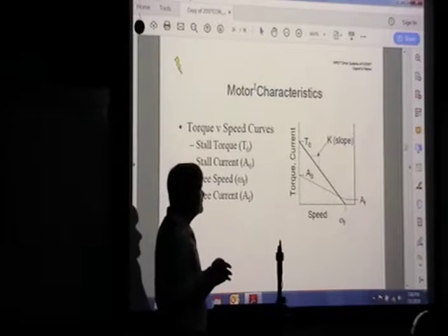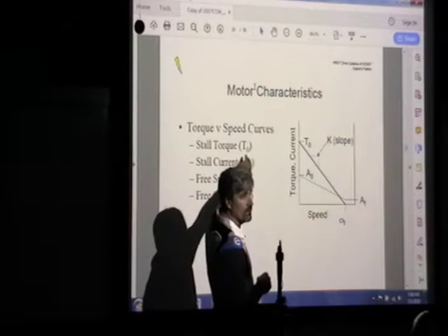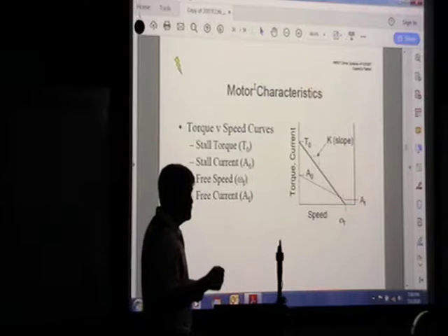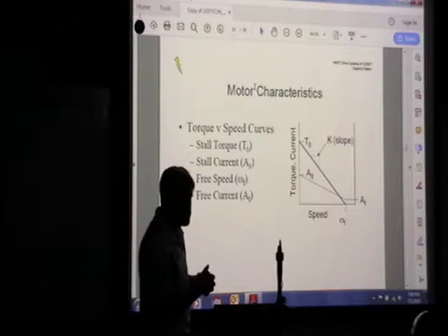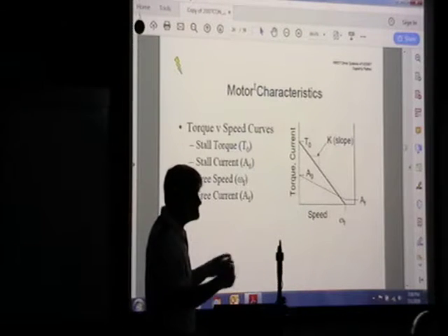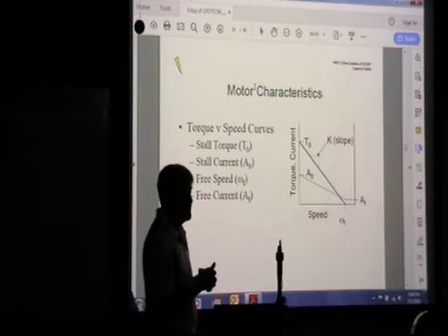So when they talk about 0 speed and high torque, that's typically your stall torque, when your motor is pushing as hard as it can, but it's not moving. And then we also learned this year what happens to the motor at that point. You're still... It smokes, because it gets too hot. It's a lot of heat.